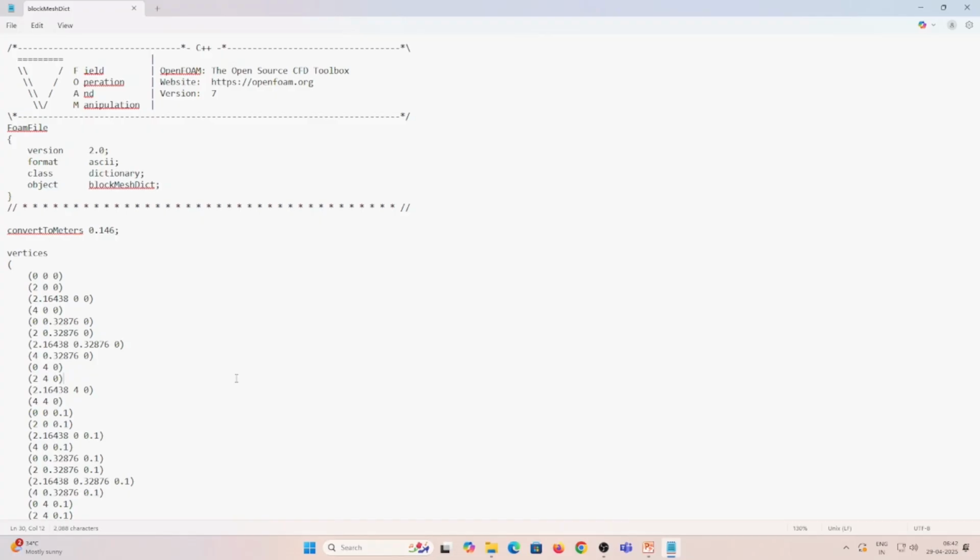But ultimately, in the actual system, things should be processed in the same system of equations, because ultimately I will be defining all my other properties as well. So if I am defining my properties in SI units, then my geometry should also be converted into SI units. For converting the geometry from any given dimension of vertices to the SI system, we will use this particular multiplication factor. Is this point clear?